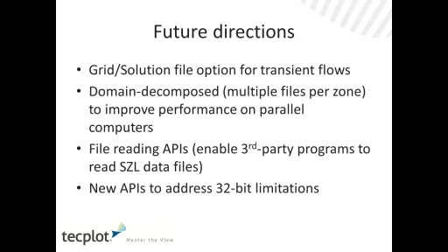But there are techniques available in Tecplot to speed things up during the rotation. You go into the options dialog and select approximate grids. We can actually walk through that. That'll speed it up pretty dramatically for you. It'll take a couple seconds to generate the approximate grids, but that's much faster.